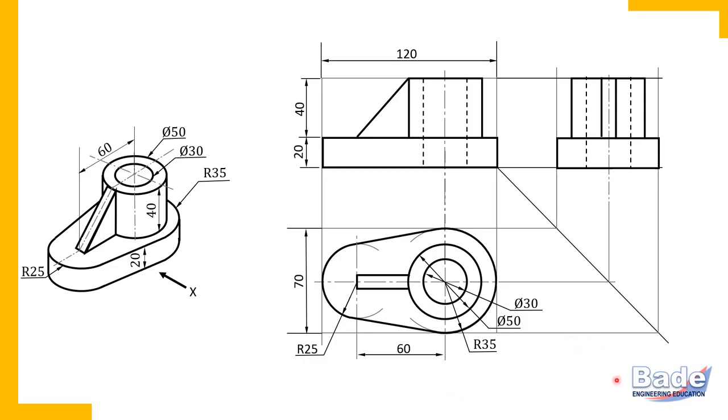Now what is very important now here, something new in this diagram, try to understand. When it is portion of a circle, semicircle, quarter circle or any length of arc of a circle, you should insert dimension with radius. So this circular edge has a radius 25. Now watch here, this circular edge has radius 35. This is how we insert dimensions for arcs of a circle.